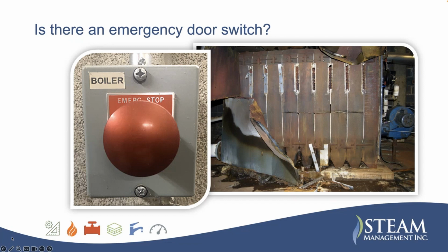The boiler on the right, you can see the cracked sections here. Well, what happened in the middle of the night, the smoke alarm went off inside the boiler room. The fire department came, and the fire department used their infrared cameras to find out what is the source of the flame, or the heat. So they found the source of the heat, and the steam leak was this boiler here. So what they did was they trained their hoses on this boiler, and it cracked every section in the boiler.